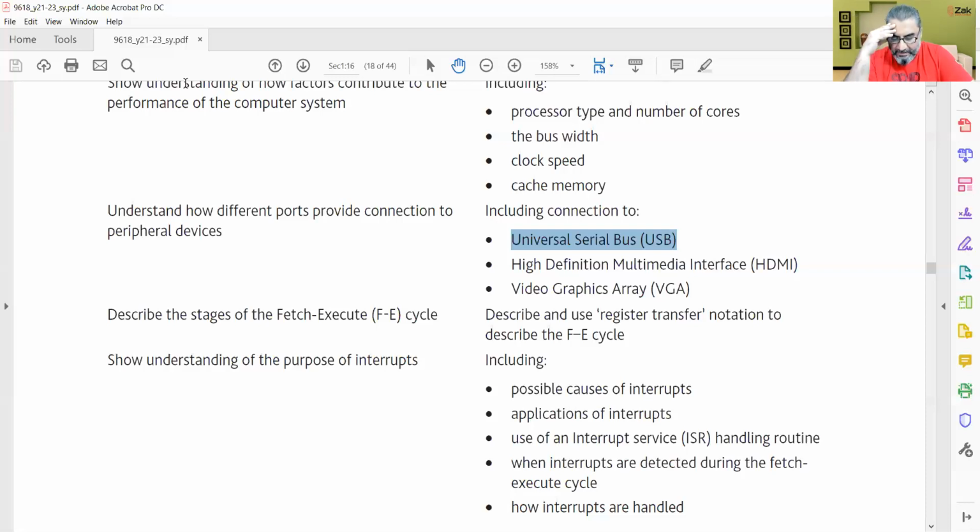Several different data transmission rates are supported. All right, it is up to 5 point something Gbps with USB-C and USB 3, 3.0.1. Newer USB standards are always backward compatible. So if you are connecting a USB 2 port with USB-C, that is fine. If you are connecting USB 2 with USB 3, that is fine as well. So they tame down or speed up themselves.